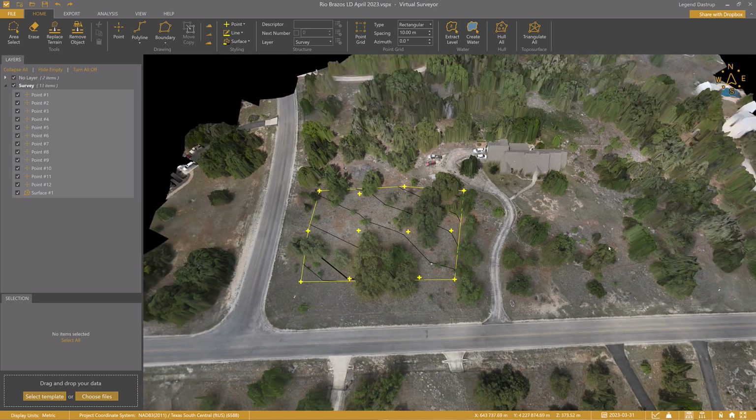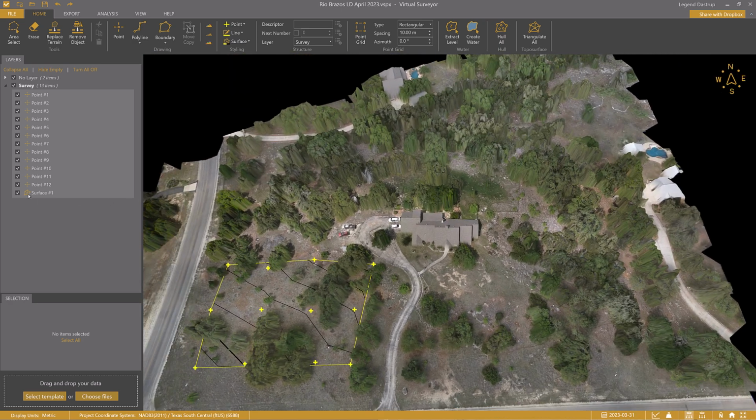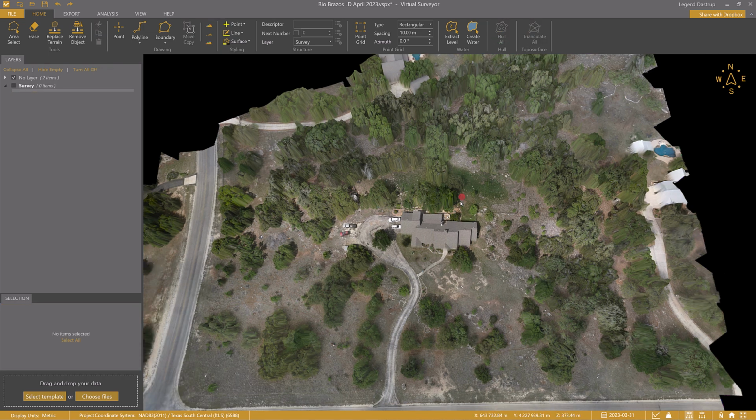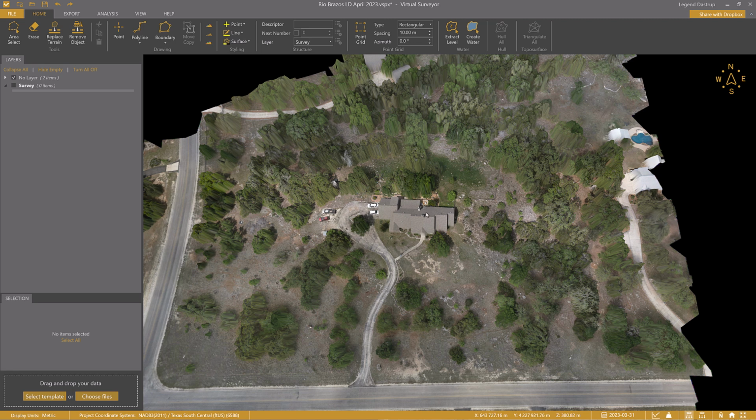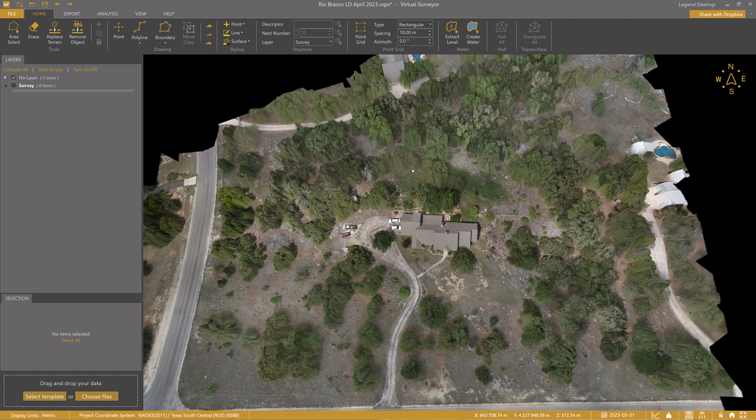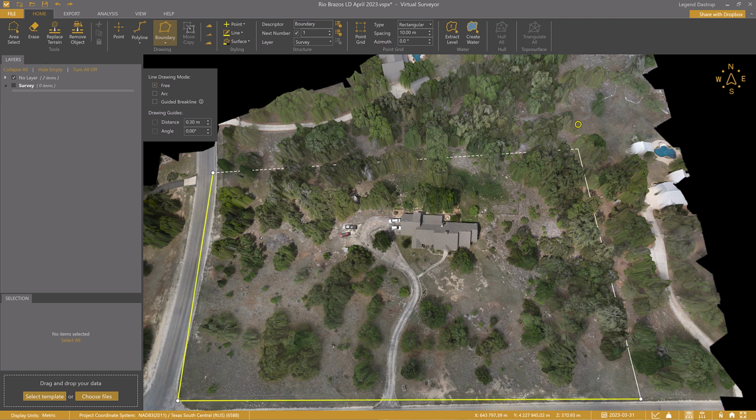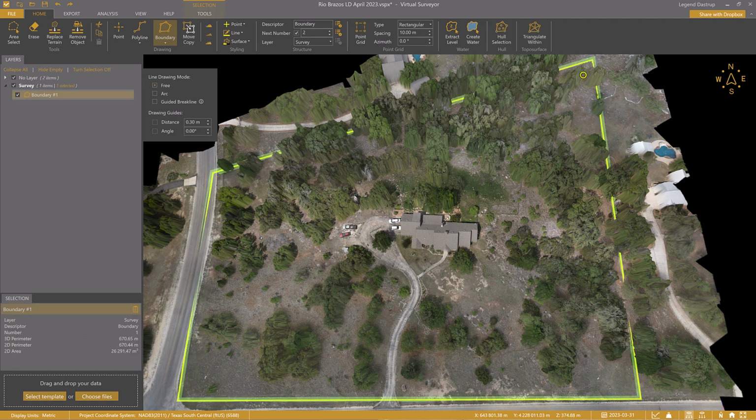Now I can show you how to speed up the surveying process by taking advantage of drone technology. I'll still use the same surveying concept, except I can get the job done much faster across a larger area while utilizing more intelligent tools. I'll use a point grid tool to have the software place points on the terrain for me. To generate a point grid, I'll need to create a boundary around the site so the computer knows what area I want to place the points in.